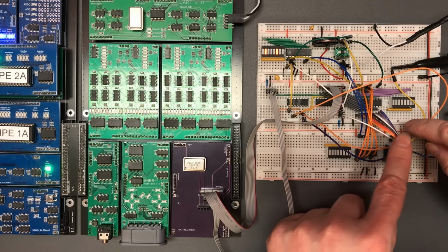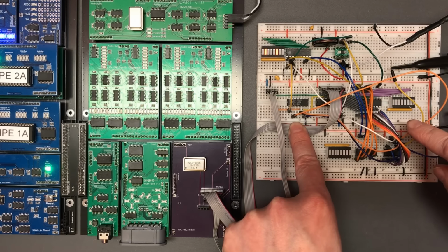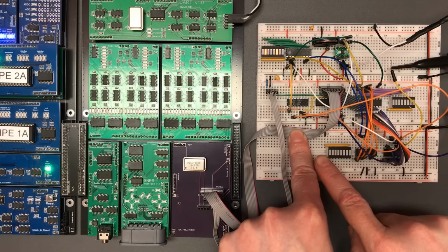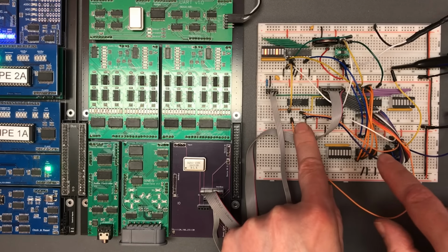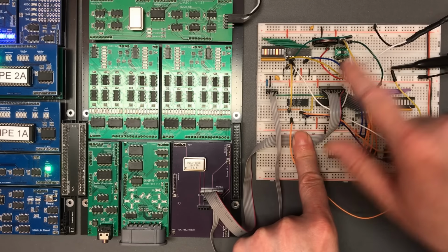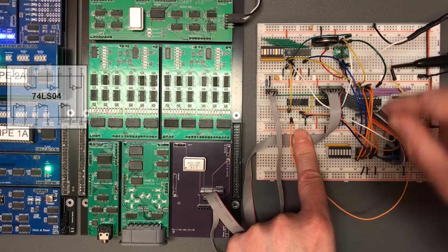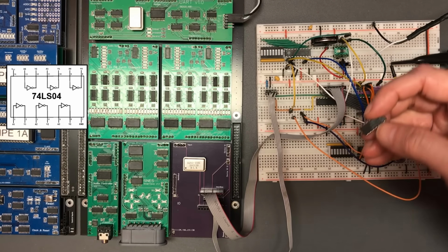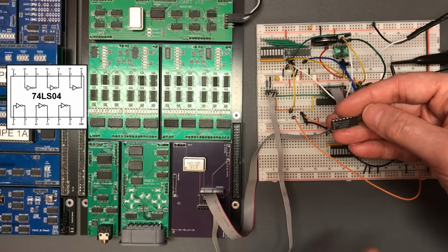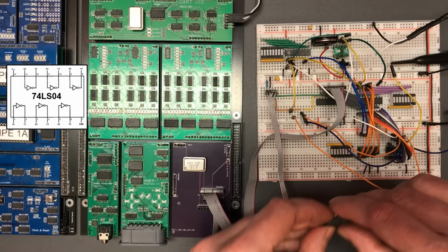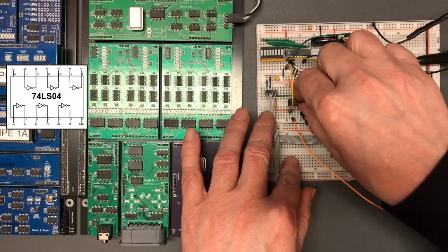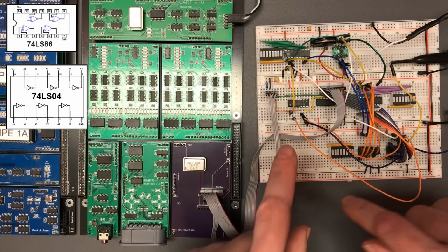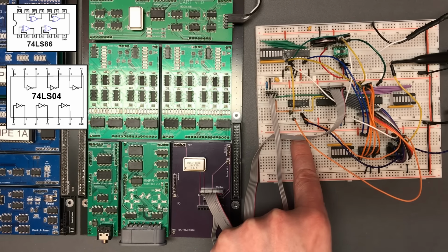Right, so at present, the clock line is going through one of the inverters, and we want to put a stop to that and drive it directly. But then we want to conditionally invert the signal that goes off to the devices. So I think we need a different chip instead of this 04. 74LS04, that had 6 inverters on it, and I'm going to swap that directly for this 74LS86. Now this has got 4 exclusive OR gates which you can use as inverters, specifically conditional inverters.